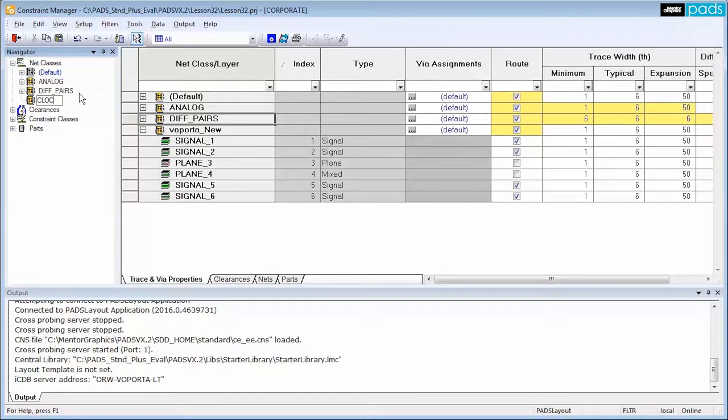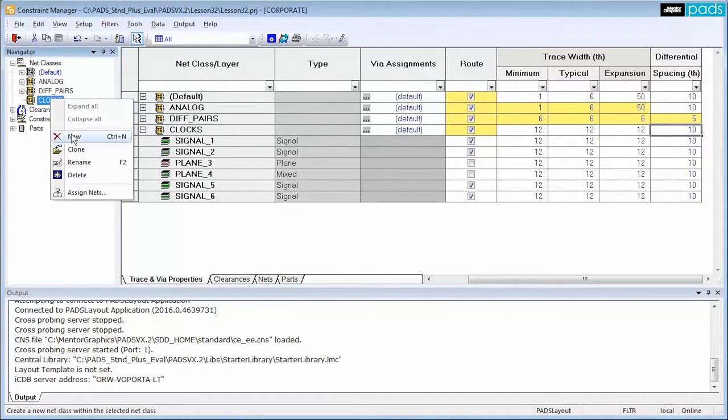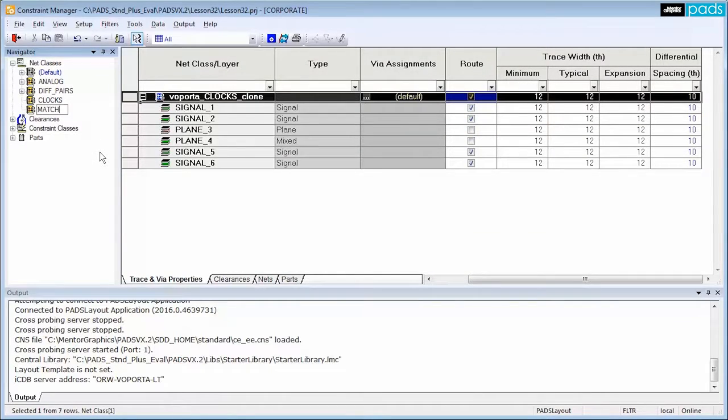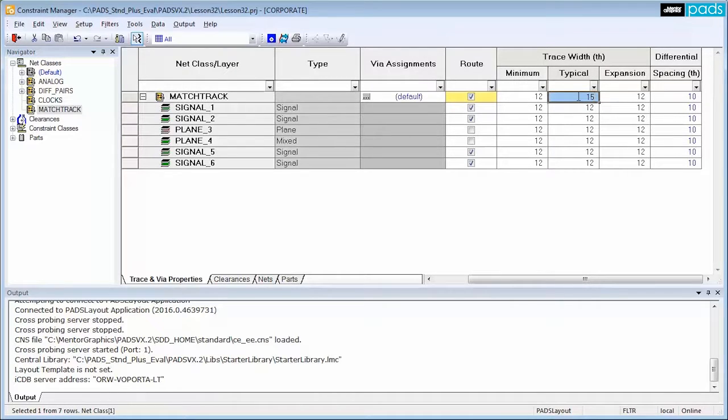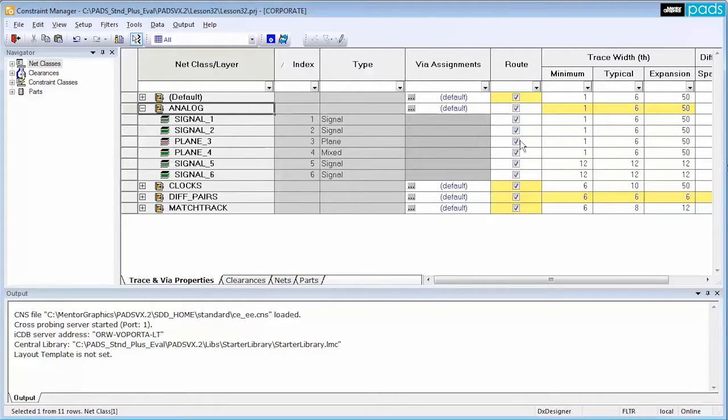Net class definitions include minimum and maximum lengths, minimum spacing between nets in the same class, minimum spacing to nets from other net classes, and allowed trace width range to maintain characteristic impedance. Layer restrictions can be set up for net classes to identify layers where nets can and cannot be routed. VIA restrictions can be set up including the maximum VIA count per net and allowed VIA pad stacks. And custom topologies can be created for individual nets that specify propagation paths from net sources to loads and terminators.